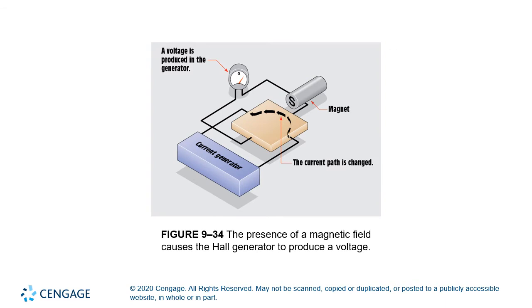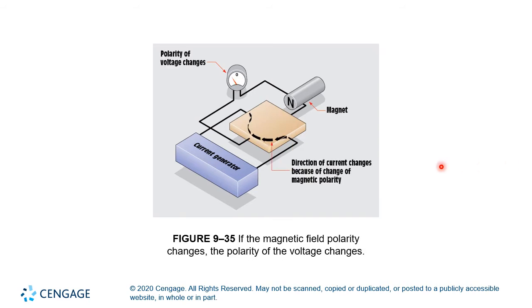So in this case here, the current is flowing through here, right? This is the current we're measuring, and its magnetic field is going to be distorted, right? That distortion is going to create a voltage, right? In this case, we use a permanent magnet to bias this in one direction or the other. One of the nice things about these setups is they actually will work with AC because we can have it go in either direction. We can bias it in either way, and it will measure the voltage. Notice it'll go positive, negative, depending on how we have this magnet set up.